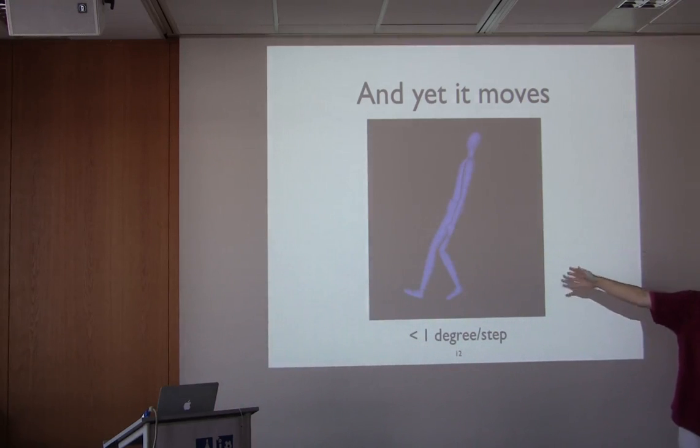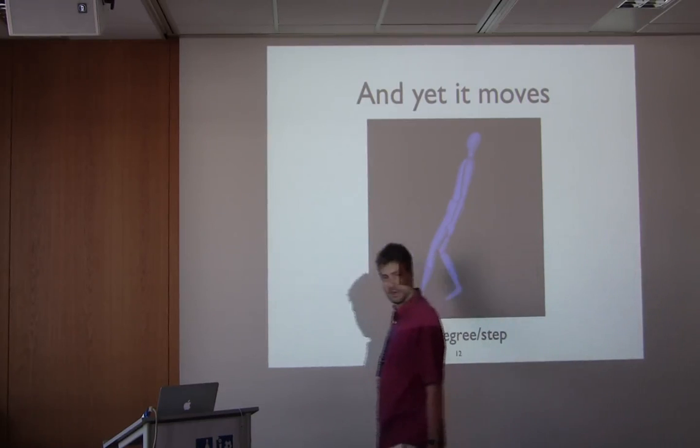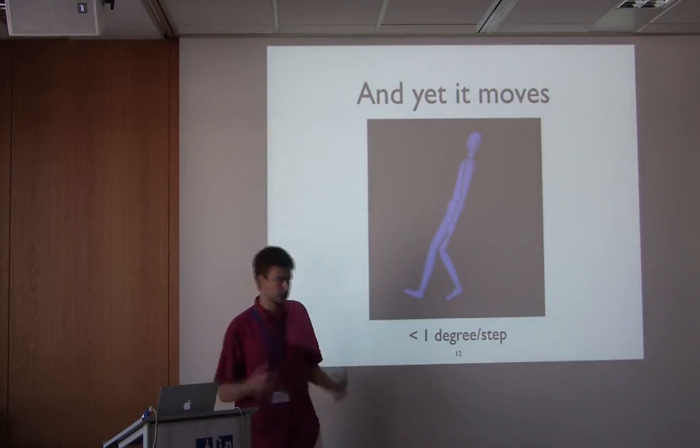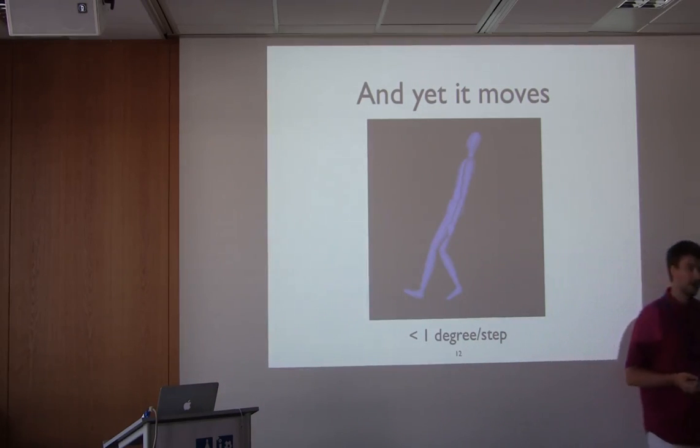Here it was a mocap motion, recorded on the humanoid replay. So that's a true walking motion. And if you do it with zero angular momentum, you turn. And when you do it now on the ground, you don't turn. Of course, that means that you have a non-zero angular momentum when you walk.